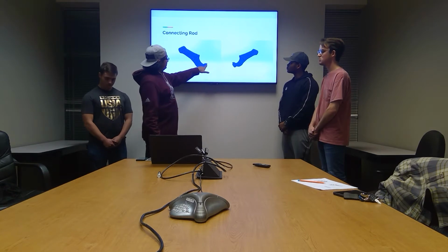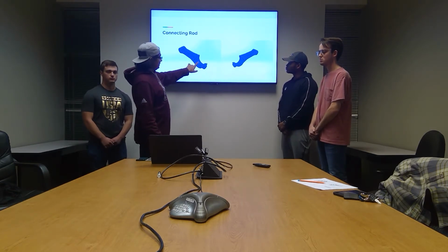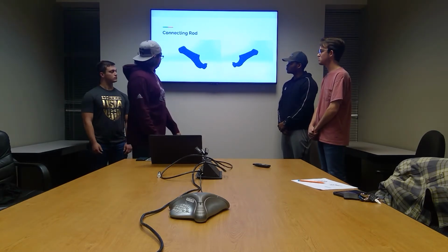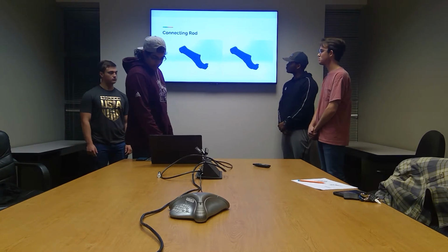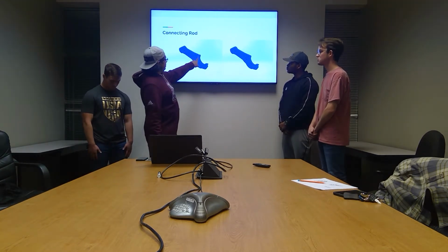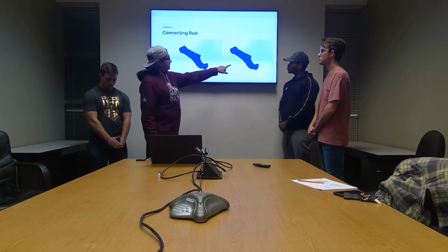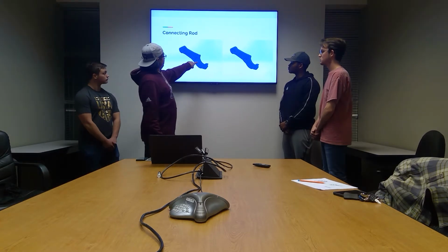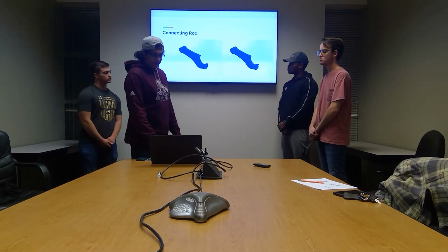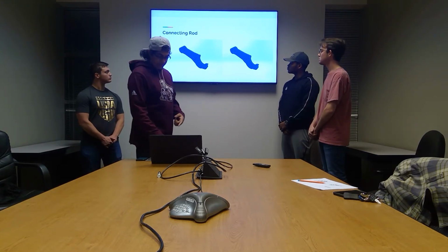I added this little cylinder bit, which is for the screw that connects the top part and the bottom part together. And then I added this little circle. After that, I finished up with a little bit of details, made the hole go through the entire part for one screw. On the next face, I made the other screw hole. And then in the middle, there's a hole that goes through the part, but not through the top face, which is why it won't be shown at the top.